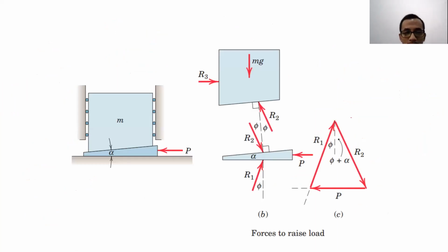So, like I said before, the friction force which is happening on the surface depends only on the normal force. Why does it depend only on the normal force? Because the one in question for the wedge is always what is the force to put the wedge in and what is the force to pull the wedge out.